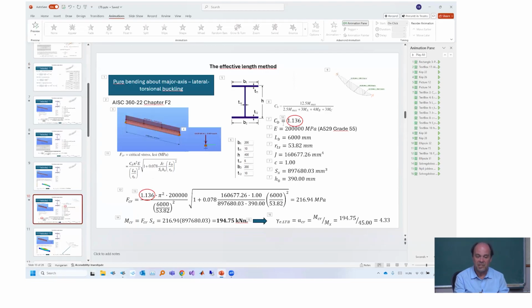Here I use the CB value of AISC, which comes from this very well-known formula, this one. Again, important, this is only applicable for uniform cross-section, as we will see later. And if you have seen the Design Guide 25, this is basically misleading. The formula speaks about bending moments, but actually it shouldn't speak about bending moments.